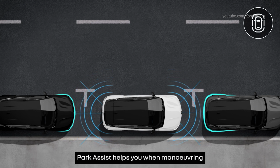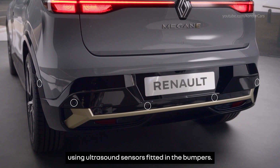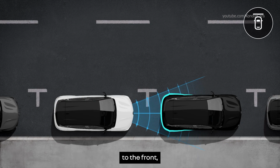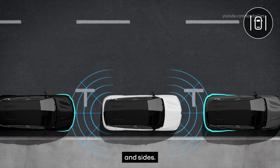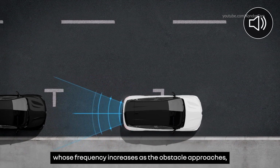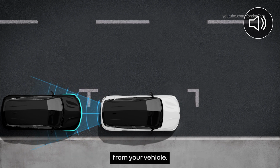Park Assist helps you when maneuvering by measuring the distance between your vehicle and an obstacle using ultrasound sensors fitted in the bumpers. Depending on the vehicle, the system detects obstacles to the front, rear, and sides. The system warns you with audible signals whose frequency increases as the obstacle approaches, becoming a continuous sound when the obstacle is around 20 to 30 centimeters from your vehicle.